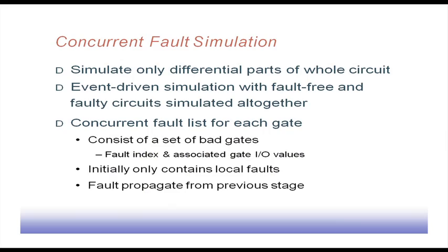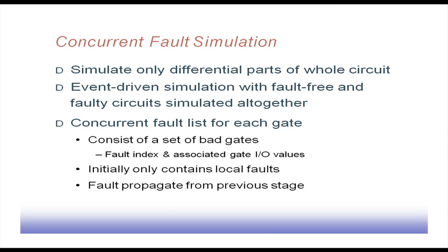So it is an event driven simulation, with fault free and faulty circuits simulated all together. Event driven simulation means that if some part of the circuit changes, then only the output of that gate will be simulated. It is concurrent because the fault free and faulty circuits are simulated together. So it combines the advantages of parallel simulation and event driven simulation policies.